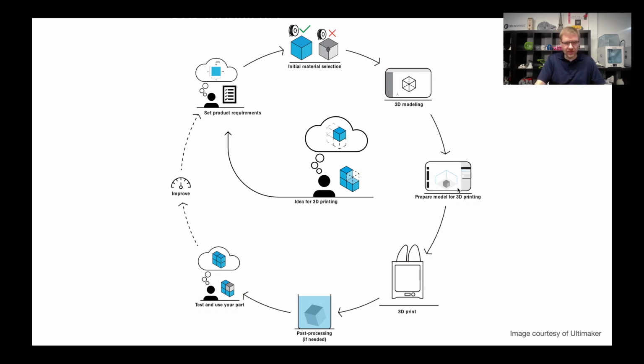All right, so you go through the slicing, you pick your settings, you get it all ready, you send it to the printer, and you 3D print. You let the printer do its work. Hopefully that goes smoothly. When it's done, there might be some kind of post-processing. It depends on what you're dealing with. For example, nowadays, a lot of people have printers with dual extrusion capabilities, and they sometimes print with soluble support material, so that if the object needs to be printed with supports, and we'll talk about that shortly, you can print with a type of support material that can be dissolved in water. So you might have to drop your part in water after it prints to dissolve away those supports.